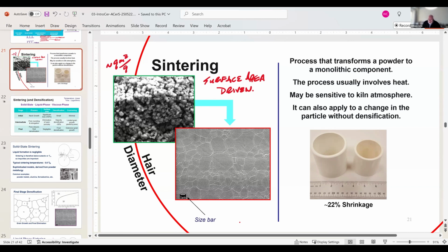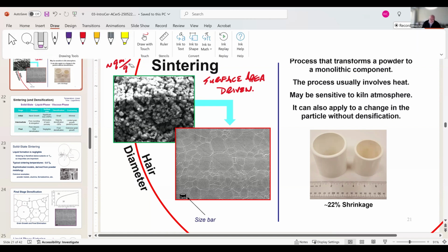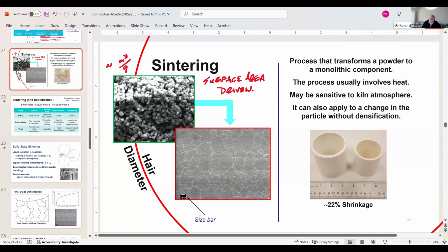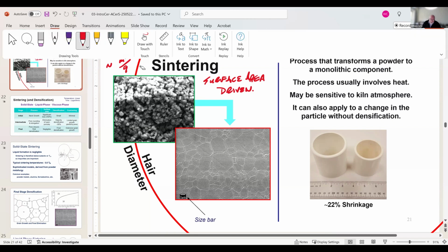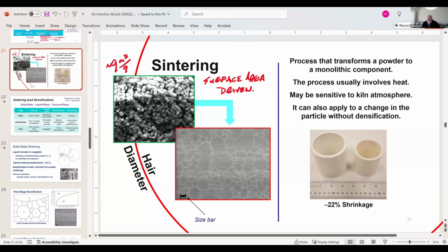And if I were to take a coarser powder that's say 1 meter squared per gram, it simply doesn't sinter. So just keep that in mind. This is highly surface area dependent, and most of this literature was generated by the metallurgy industry in the development of sintering of powder metals and then applied to ceramics at a later date.